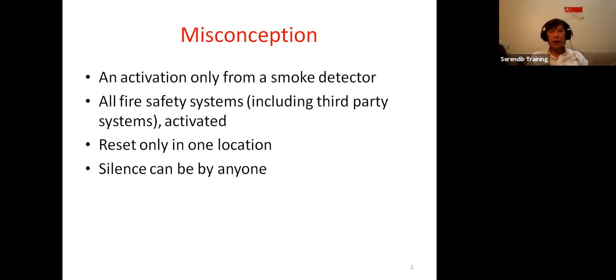And like I mentioned earlier, all fire safety systems have various ways or configurations in which they will be activated or deactivated. Very often, I feel consultants will jump into cause and effect that is way too simplistic, where a single activation of, say, a smoke detector activates every system. That includes releasing the security door lock, not only releasing the lock, but opening the door automatically. All lifts need to be recalled. Every single system needs to be activated all at the same time. This is not correct.